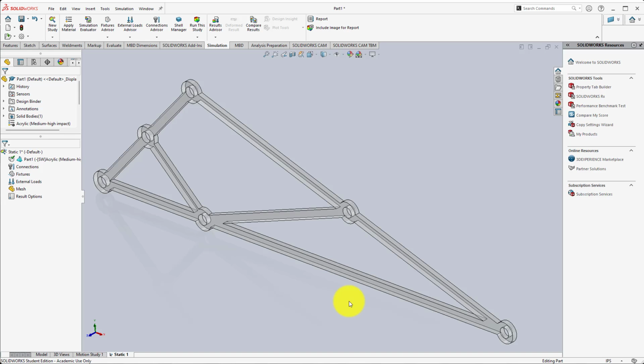You don't want to go putting loads and all these kind of things on, just like we don't want to draw our part and then change units, because if you draw something at 1 inch and it was actually 1 millimeter and you think, I'll just change the units, it's still 1 millimeter. It'll just be on the scale of the inch system. So we've got to do those settings initially. So we are in inch system, PSI, something that most American students are going to relate to a little bit more than the newtons and such that we're going to put on here.